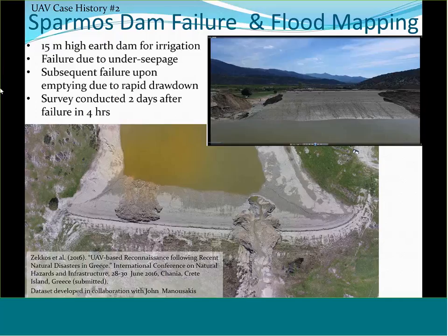The downstream side of the dam is heavily eroded, and there is clear evidence of piping, and at some section of it, essentially it washed away. And there was, of course, water impounded in the back that rushed out and completely eroded the failure location. As the water in the reservoir dropped, there was a classic rapid drawdown failure, which you can see in the left side of the picture.